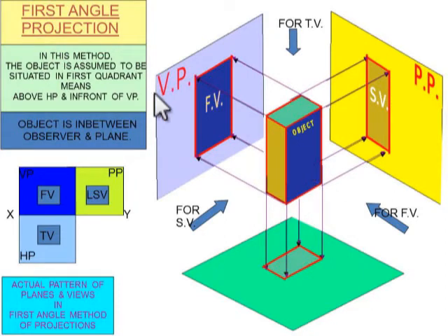In this projection, it is mentioned as first angle projection. Based on the quadrants where the objects are present, you can classify the projection as first angle, second angle, third angle, and fourth angle. While 4 angles of projection are possible, only first angle projection and third angle projection are followed. In India we follow first angle projection.